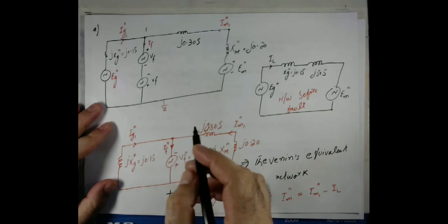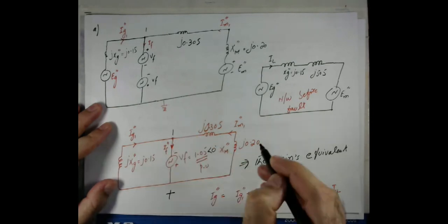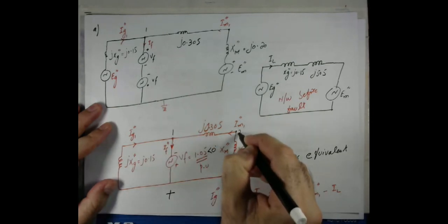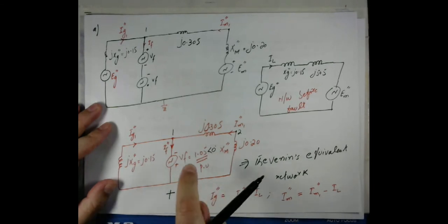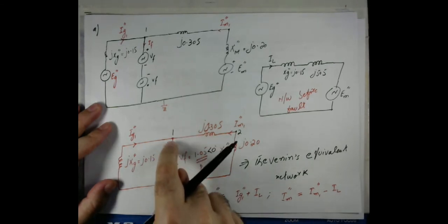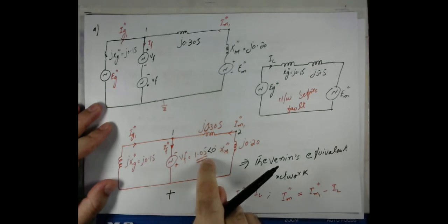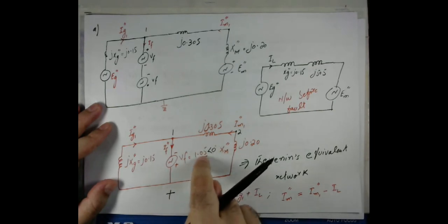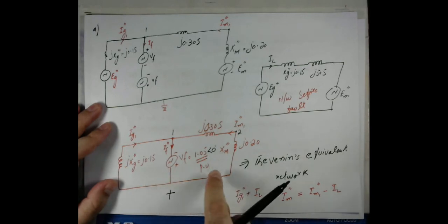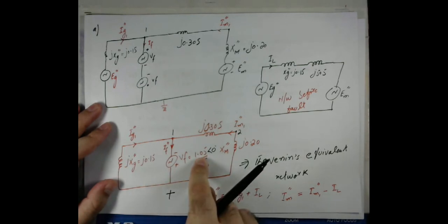So at this particular bus, which is bus number 1, that is bus number 2. The voltage at bus number 1, because the fault occurs at bus number 1, will be taken as a reference. We assume that the voltage is the same as the pre-fault voltage, which was mentioned in the question.